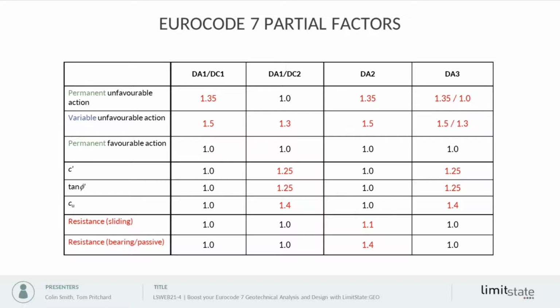And the revised version of the Eurocode is to some extent trying to take this on board for users of numerical methods. But we're going to focus on the first column, where we apply factors to actions, and there are no factors applied to any resistances. Now you'll note I've changed one of the bottom rows from resistance to action effect. And an action effect in this type of analysis is assumed to be something, a force in a structural element generally, that we calculate at the end of the analysis. So that might be a bending moment in a retaining wall.